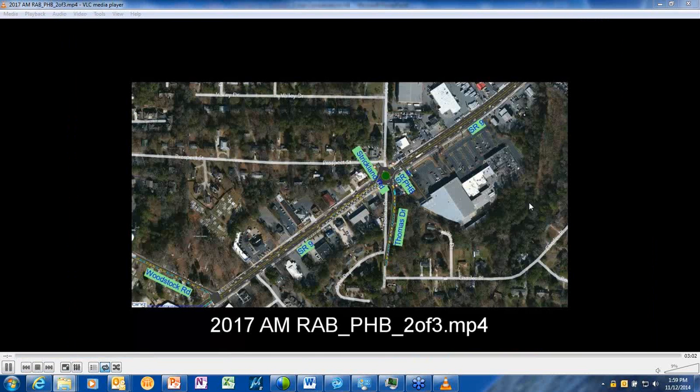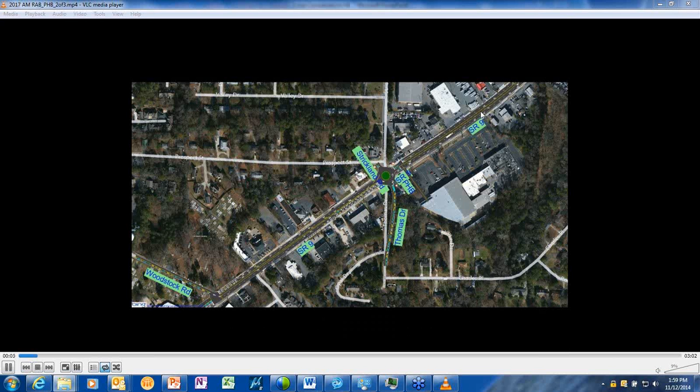This is some Synchro, and it's in a signal-coordinated network. And there's a school here in the video that shows there's a pedestrian crosswalk for the school. And we determined that the pedestrian volume was so high during the peak times that we would have to use the signal to meter the pedestrian traffic, because if we left the crossing uncontrolled, pedestrians would be impeding the traffic throughout the peak hour, or at least the half hour at school times. And that would impact the roadways sufficiently that the signal was actually used as a metering device. And that's not how we started the analysis.